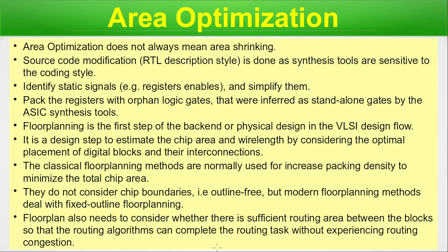That means there are the macros, we need to place standard cells, we need to place our other blocks, everything, and at the same time we should not have congestion. That means one area is too dense and another area is too less dense. So everything should be balanced, and that is the purpose of the area optimization. And at the same time we need our timing performance, that means the performance of the chip, as well as all sorts of power in check.